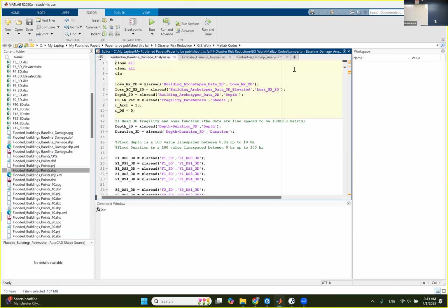I have here the flood depths. I have here the losses, and the losses up to 100%. Let's say this is 50%. And this is the loss curve, the original one, something like this, all right? And you did some mitigation to the building. What kind of mitigation? Let's say you elevated the water sensitive components, like you elevated the AC unit, you elevated the electronics. Like 6 hours before the flooding, the flood warning, you try to elevate every water sensitive component.